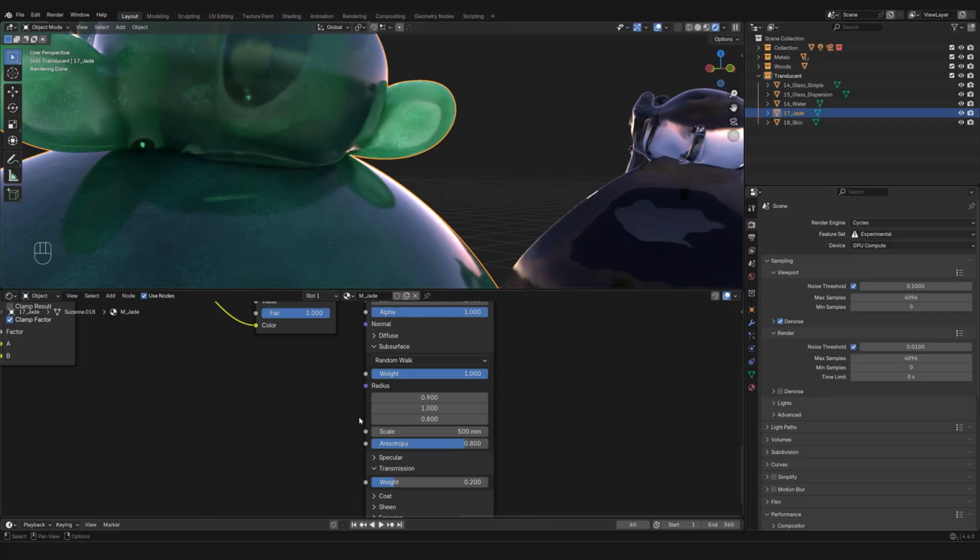If you look at these three values, you should guess that they are RGB values, because we have a purple icon here that tells us that we are dealing with vectors. And so you can guess, just like if this was a color, that by having the green channel higher, this is leaning towards green. But because the other numbers are not too far behind, this is a color that leans towards green but is very close to white, which is creating this kind of effect that echoes the green color of the material.